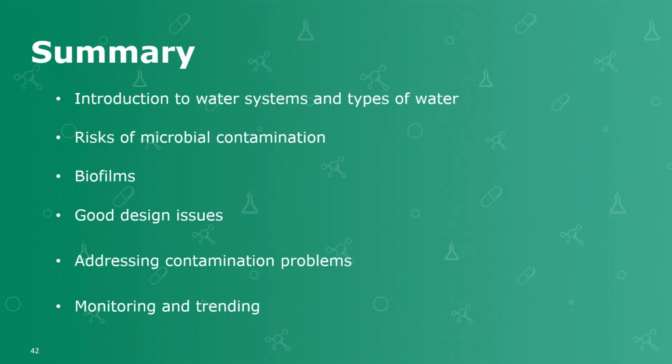So, in terms of bringing this webinar to an end before we go on to Q&A, we've looked at some of the risks around pharmaceutical water distribution systems, and touched upon that the primary risk is microbial adhesion. This goes back to something I said when we were looking at disinfectants: microorganisms, if they have a choice, prefer being on surfaces rather than in a free-floating or planktonic state.